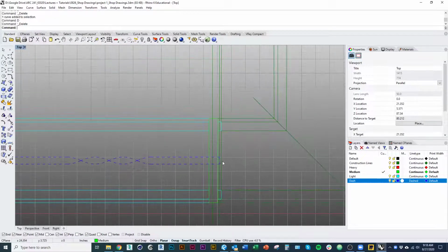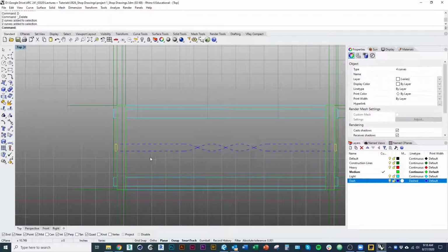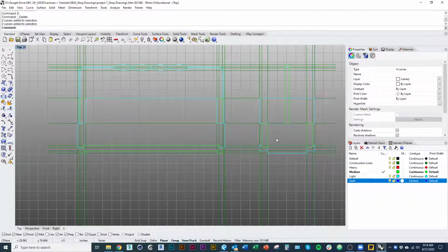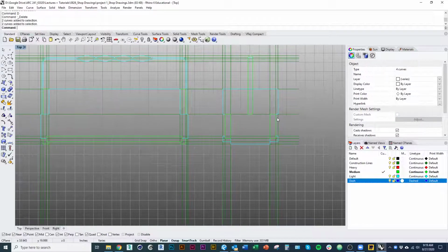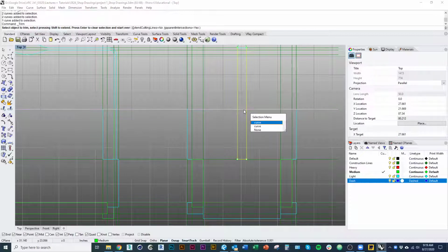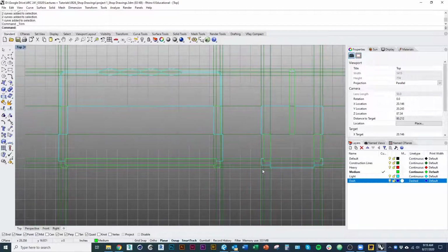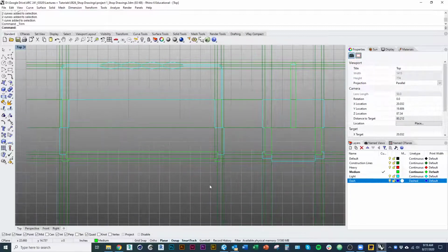And so that gives you a sense of how we would go about this. Actually, I should point out that up until now I've been line weighting just the way you would when manually drafting. My medium is obviously a heavier line weight than my light line weight, and I've been working by putting certain lines on those layers depending on how close they are to the picture plane. So if we're looking at the end of the box, these parts that stick out are a little bit closer than that side. Same is true of my handle. I should trim that line right there. So I've just been working in 2 line weights, and we can add another one later if we find we need it.